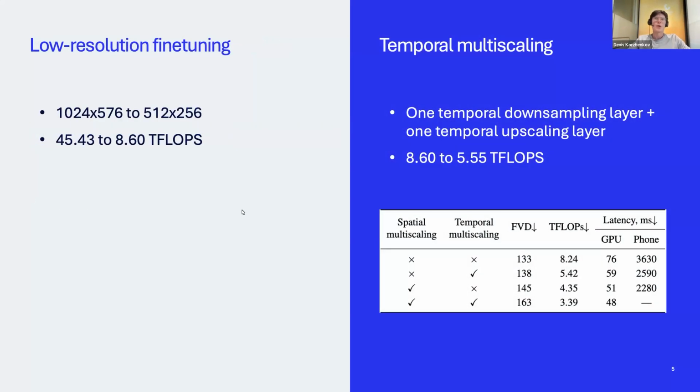So first of all, the Android NPU has a very low amount of available memory, only 8 megabytes, if my memory serves me right. So unfortunately, we found that it is necessary to decrease the resolution of the output video to fit these memory constraints. So our first step was to decrease the resolution from 1024 pixels to 512.